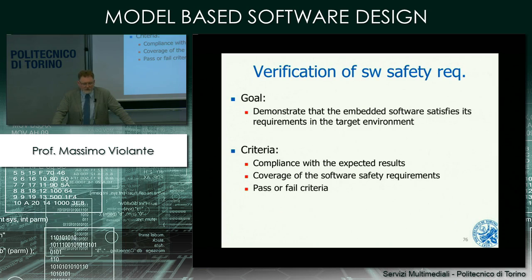Now, when verification of software safety requirements has to be addressed, you move into the target environment. So your software is not going to run on the PC, it's running on the real hardware or on a suitable model, physical model of the real hardware. And here you have to take into consideration the real-time aspects. When running the software on the PC, timing is not relevant because you cannot have the real hardware. Your PC is much more capable than the hardware that you have in your electronic control unit, where your software will be deployed. So all the activity that you do is basically not able to consider the time in which operation will take place in the real environment.